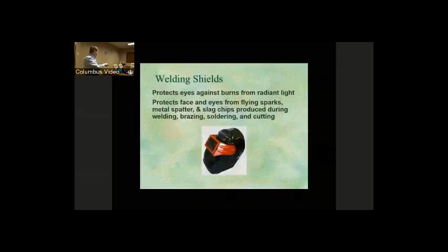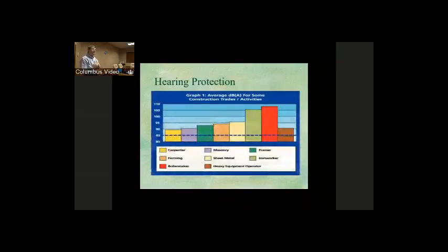Welding, cutting, and burning, again, you have to have the appropriate welding helmet with the appropriate lens, minimum of 10, rating up to 12 dark. That way, if somebody is doing any kind of arc welding, they have the appropriate helmet. Also, if you're doing welding, you need fire-resistant jackets or clothing or sleeves, and fire-resistant gloves at the same time.